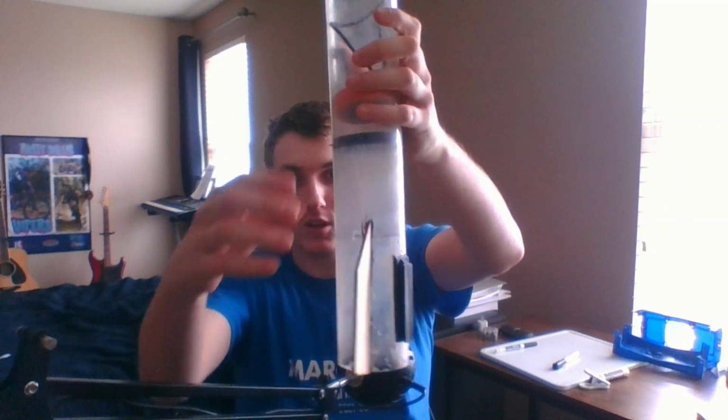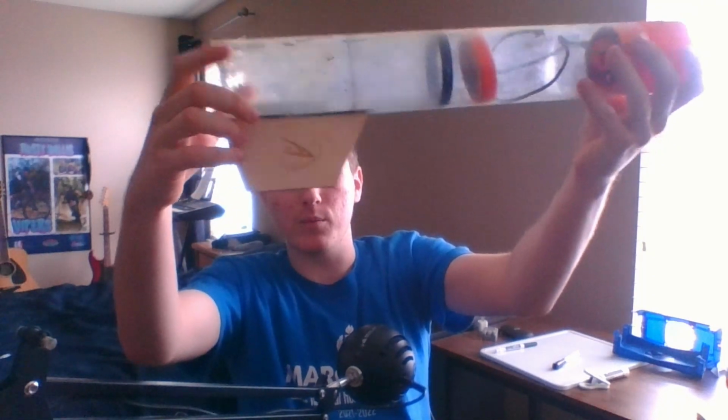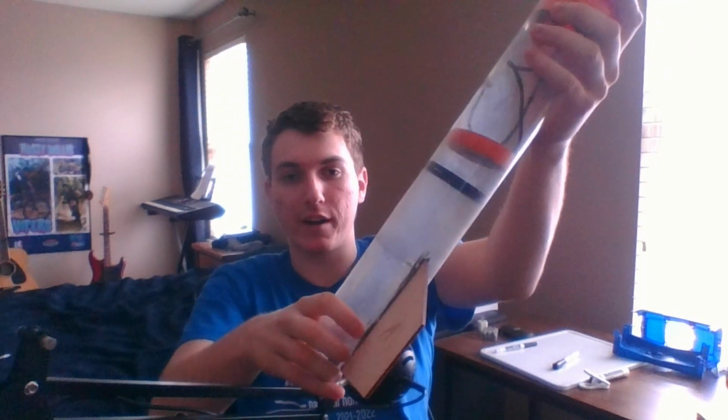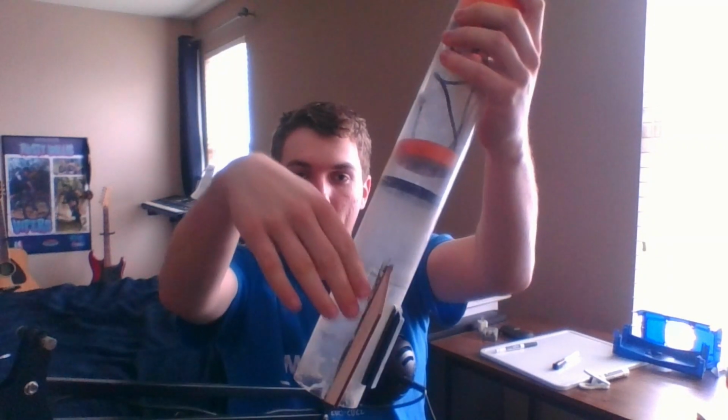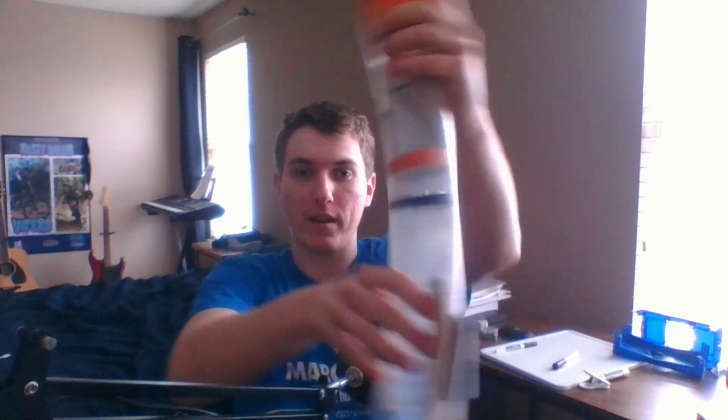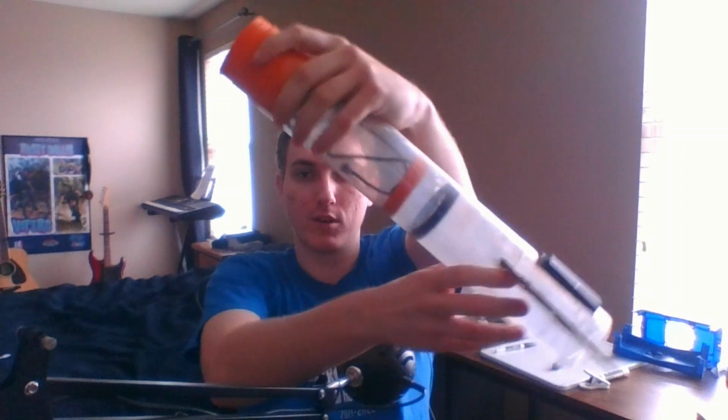So let's say the rocket gets a sideways force. Oh no. You notice how more of the fin got exposed to that perspective? So that's going to cause that drag force to correct it that way, and it'll oscillate and then go straight again. So what the rocket is constantly doing is oscillating left and right, left and right, a little bit until it gets perfectly straight. But in reality, it's always oscillating just a bit. Even if it looks straight to your eye, it is oscillating just a bit.